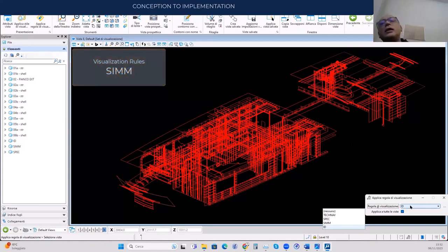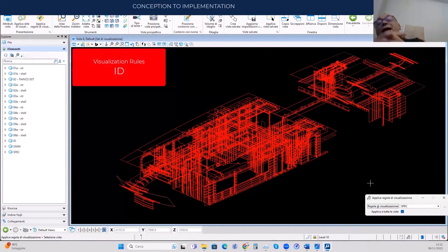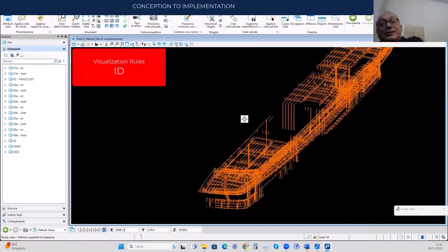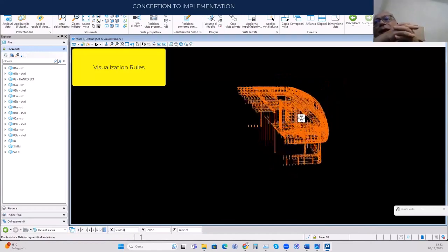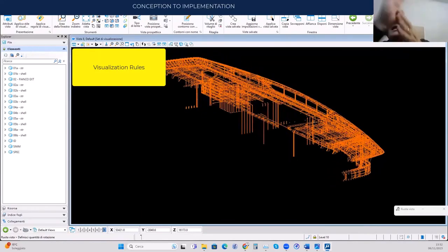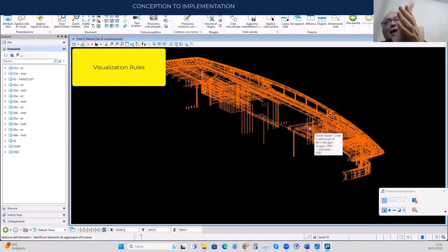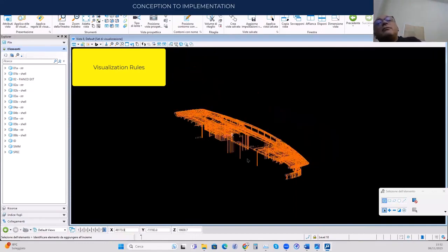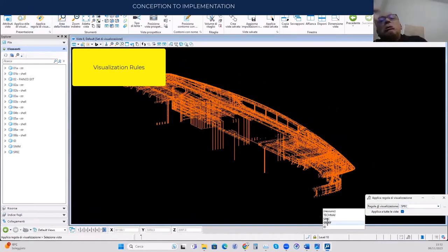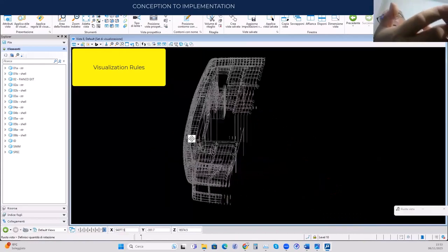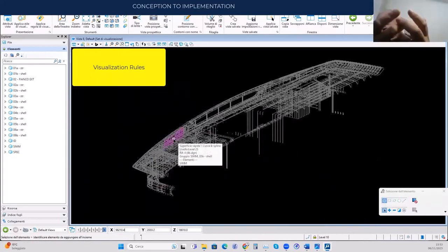They are a simplification for modeling. It starts by separating what is specular with respect to a plane that in naval terms is called the diametral plane. In practice, the line is a plane that is central to the whole boat. Symmetrical pieces are pieces that look at each other in mirroring. So the pieces on the opposite side do not have to be generated autonomously. It is simply the mirroring projection of a piece. Then once you define all the symmetrical elements, the mirror pieces are already described. They certainly don't need anything else.